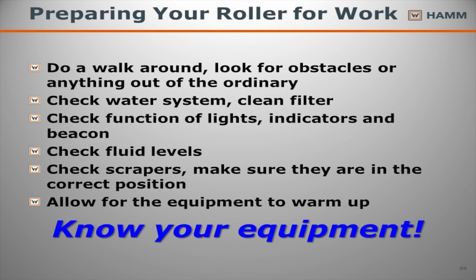So when you look at preparing your roller, you want to make sure we do a walk around, looking for anything out of the ordinary. Check the water system. Like I said, the water system and the scrapers are the two most important things on a roller. If they don't work and the scrapers are worn out, we're going to use a lot more water. You use a lot more water, you're going to spend more time behind the water truck than you are behind the paver. And the paver's not going to wait for you, trust me. Check the lights. More and more people are doing night work, so we're going to have to check the lights. Fluid levels, make sure those are all where they need to be. Again, check the scrapers and make sure they're in the right position.